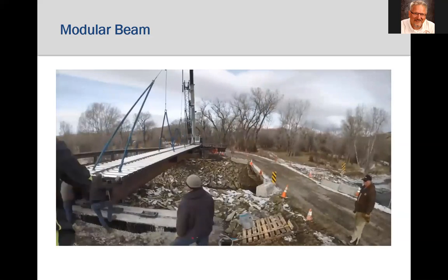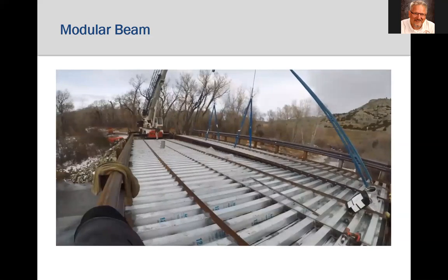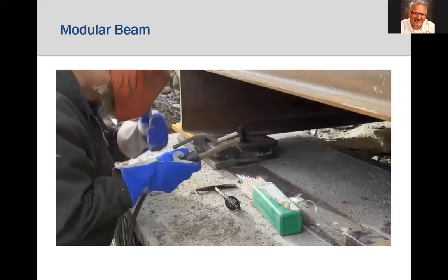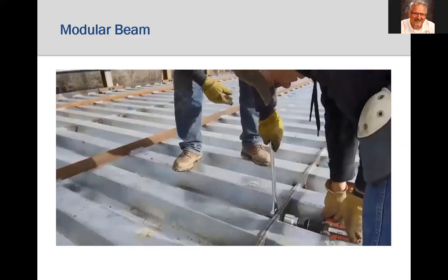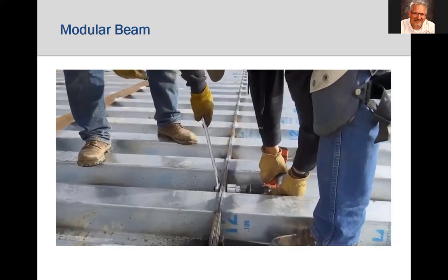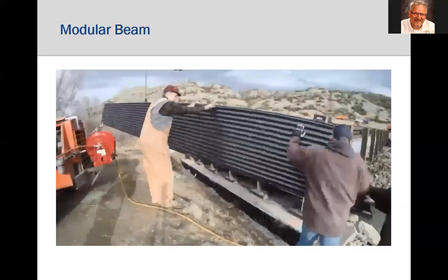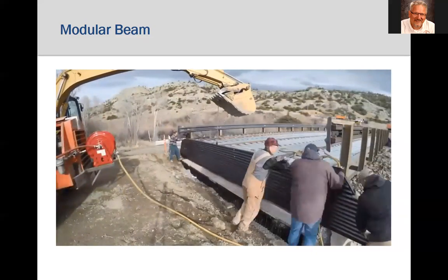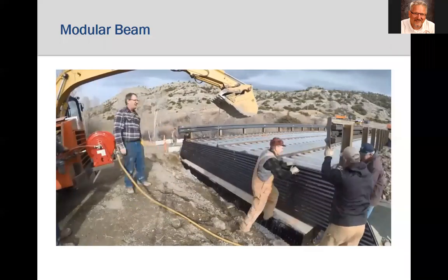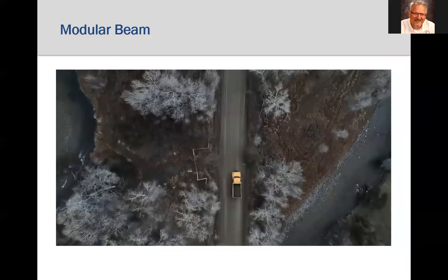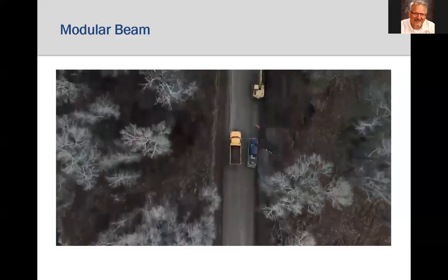Modular steel bridges are simple to install based on showing up in component form and simply bolting adjacent modules together to achieve your width and length, and utilize a steel back wall to protect each end of the bridge and provides a decent place to build your road approaches.